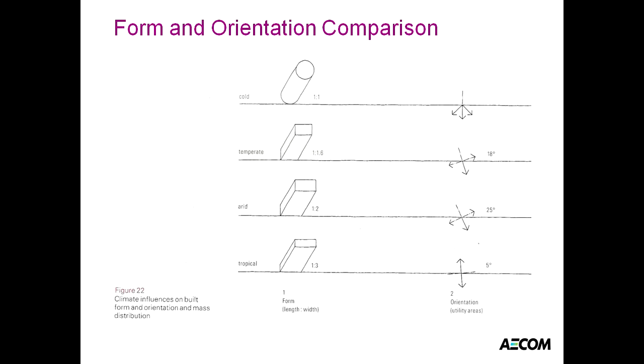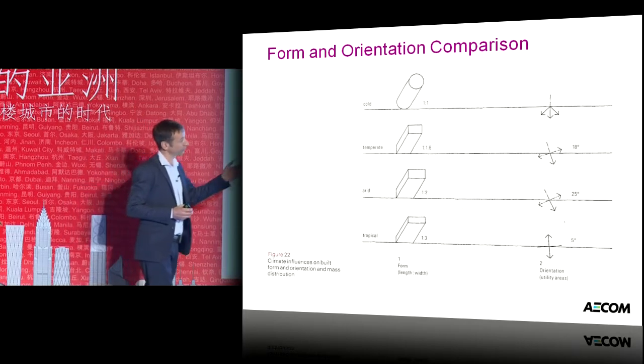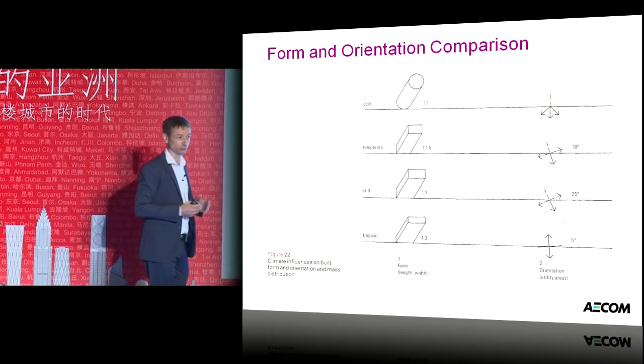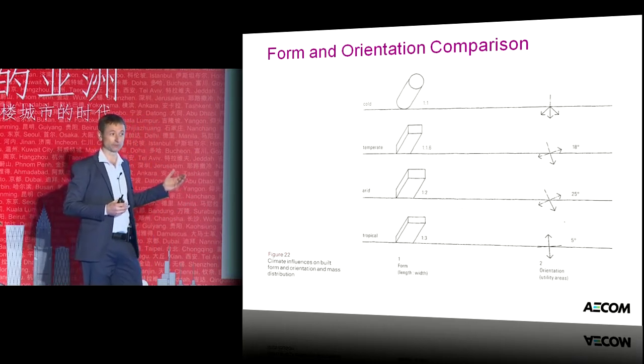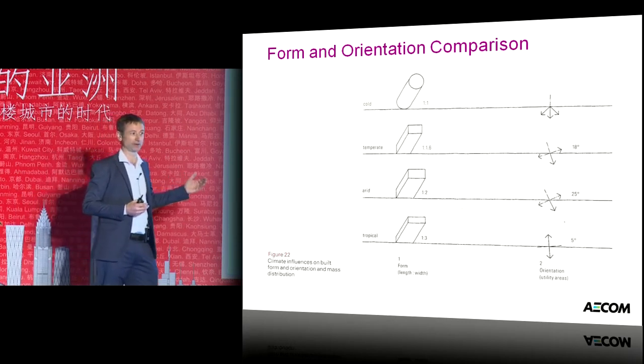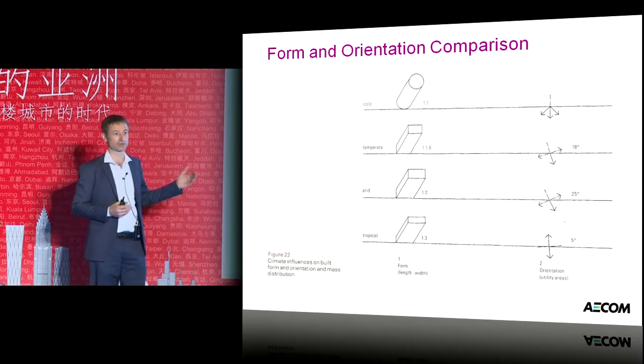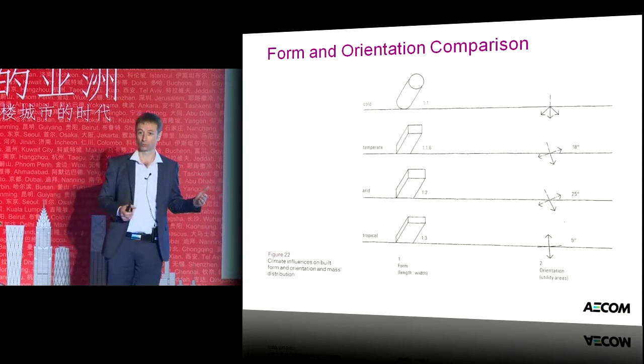And then, of course, if you look at the tropical climate, as you start moving to the lower latitudes, the sun is rising first thing in the morning, and it's directly hitting onto a building, and then going directly overhead. So then it's setting again in the west, and it's directly hitting the building. So having a very small facade on the east and the west has less of an impact on your building, and it makes a lot of sense. And then, of course, the orientation of that building, just to make sure that you get the benefit of that. So it occurred to us, well, why don't we actually put this to the test and do some modelling to demonstrate what is the benefit that you're likely to get in today's buildings, where the facade is a lot better and also where the air conditioning systems are a lot more efficient.